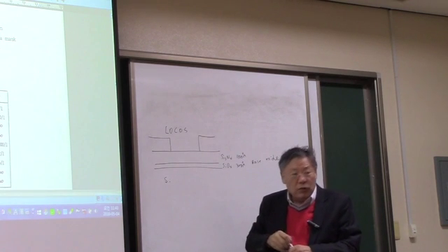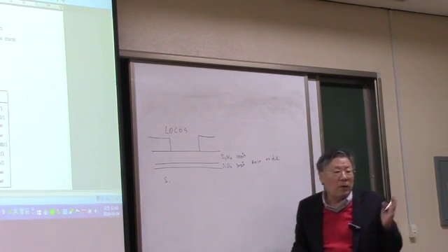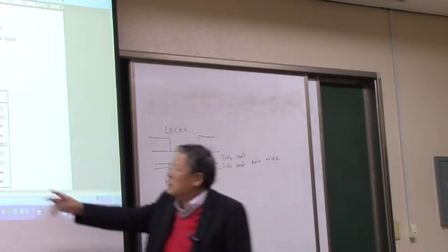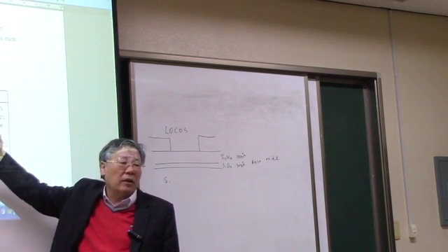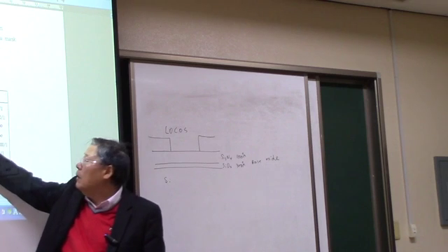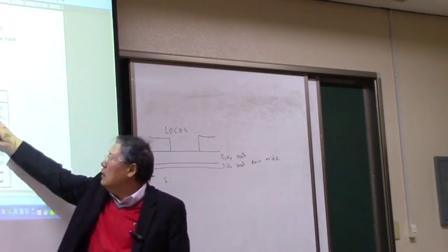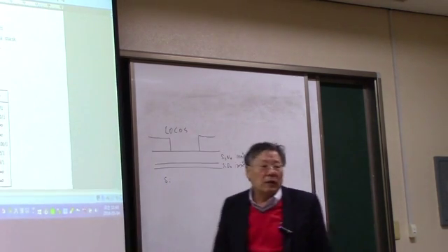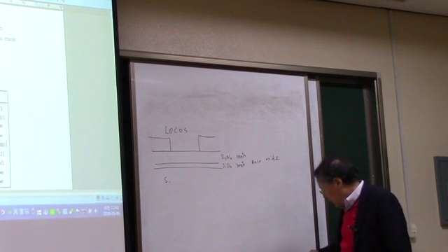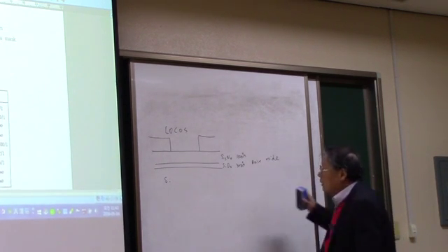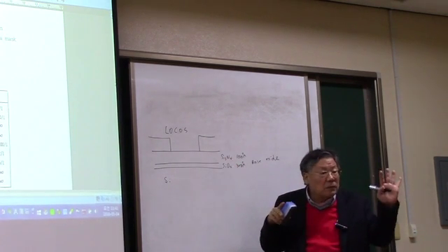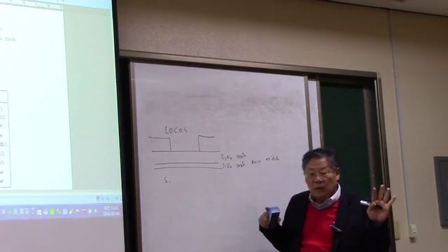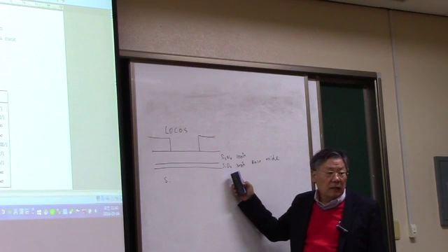Now, if you want to use the barrel type reactor and use the gas CF4 with the O2 addition to accelerate the etch rate, for example, then it says the selectivity is 4:1. So that means the etch rate of silicon nitride is 4 times faster than the silicon oxide.